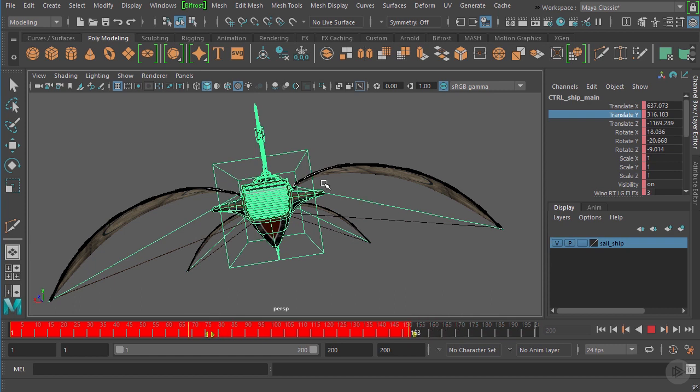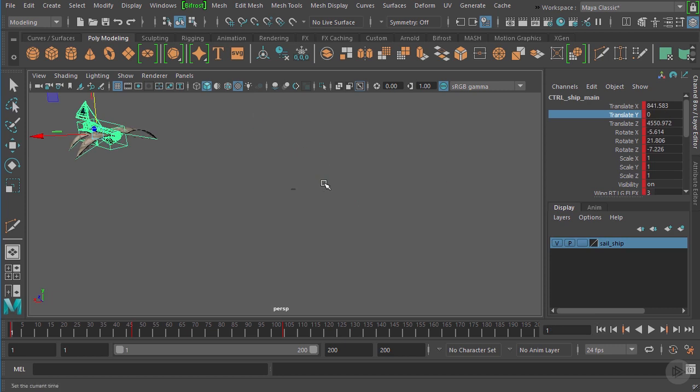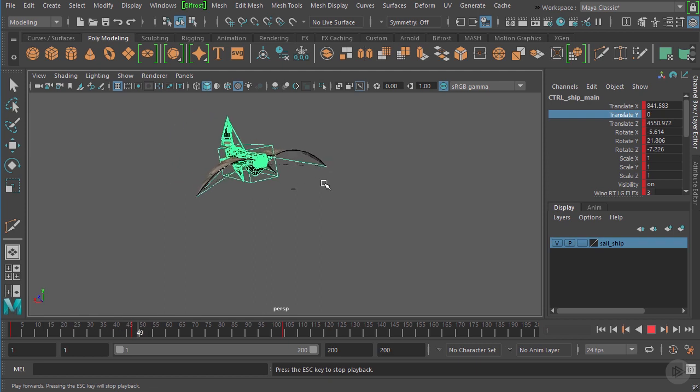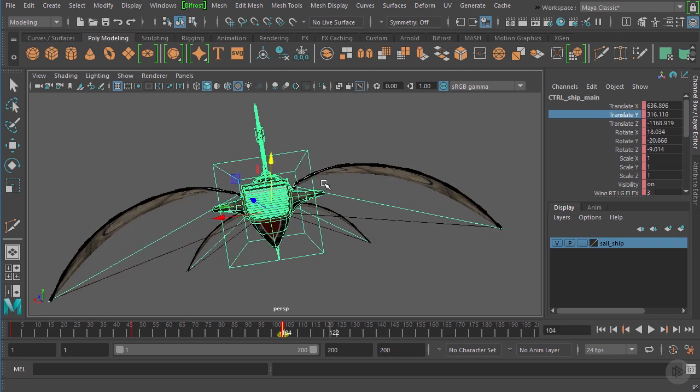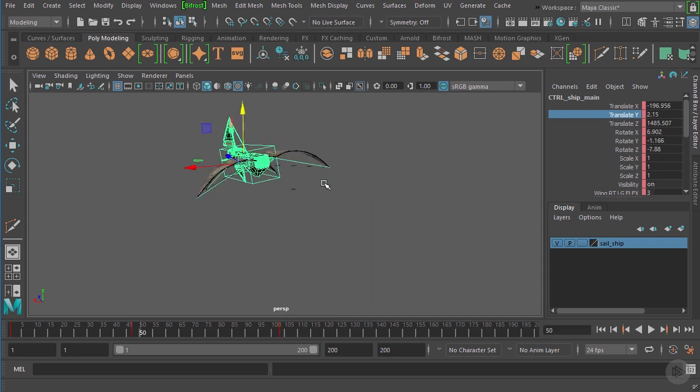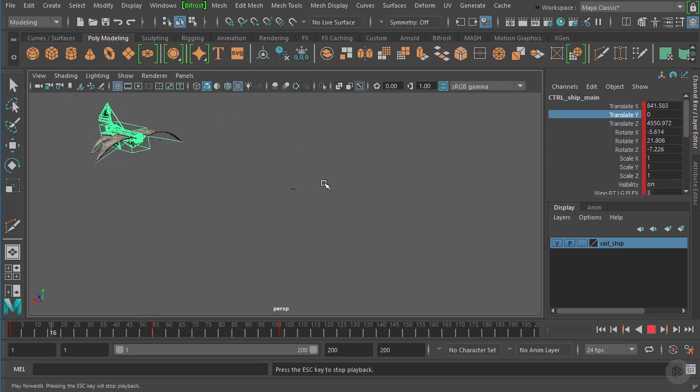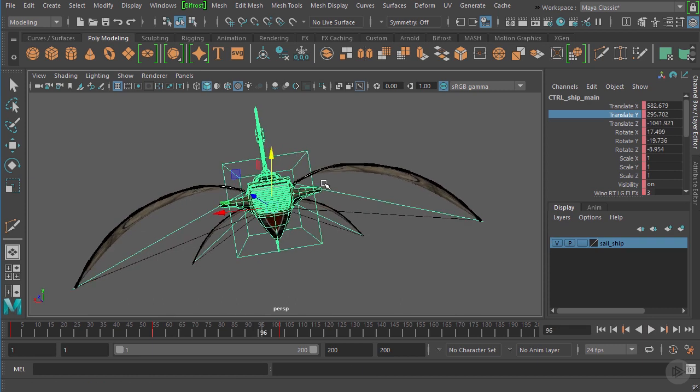I'm just dragging those down, and you can see the distance between those keyframes is shrinking. If we jump back to the very first frame and hit play, it's going to happen much quicker. We can also select those keyframes by hitting Shift and move them individually. So if I wanted to move this particular frame, again, more space between the keyframes will make things take longer, less space will make them go faster.